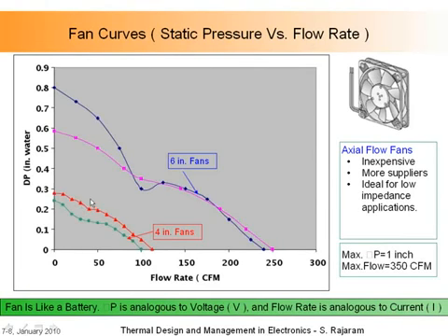So we do CFD analysis. We look at pressure drop over boards, pressure drop over heat exchangers, ducts. All of those are taken into account, and then matching that with the fan curve, and that's how we select the right fan. But ahead of time, we know which one. The thing that I want to point out to you is this particular fan, the large fans. You notice it has not a monotonically decreasing shape, but something that has this wavy pattern in the middle, and that's a very critical design parameter,